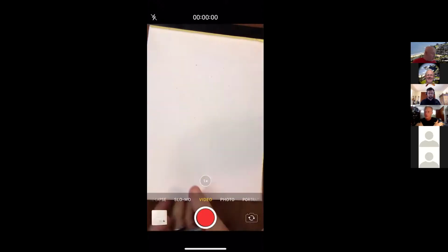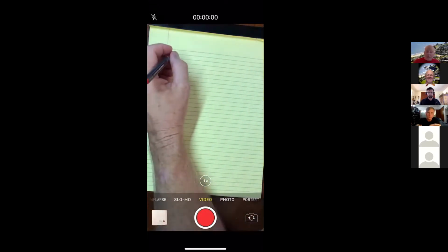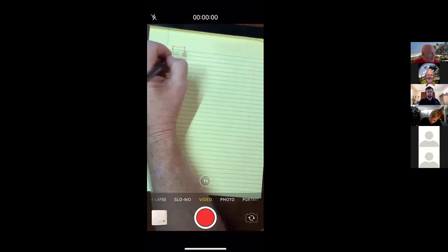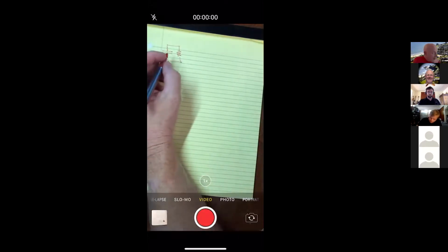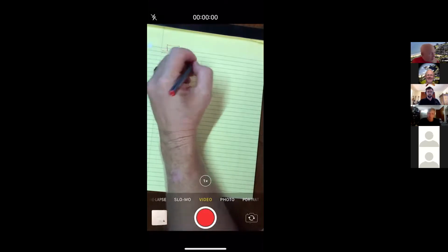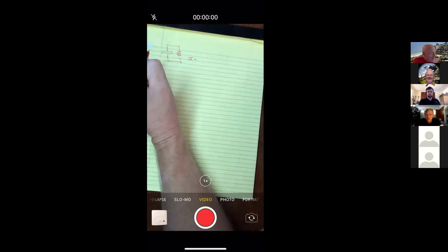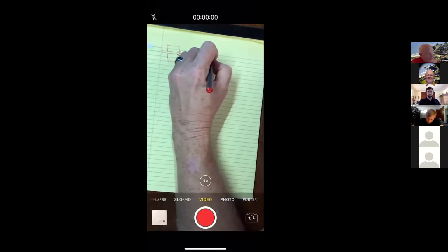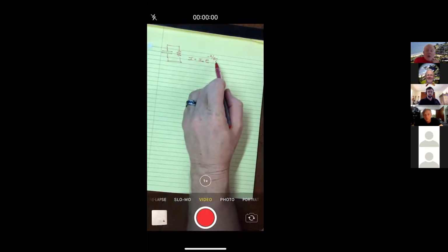Now, let me encourage you, especially for both homework and for a test, to remember that we solved a discharging capacitor problem. We said if you start with a capacitor and you run it through a resistor, the current starts off at some initial current and then decays away with an exponential, with what we call the RC time constant.